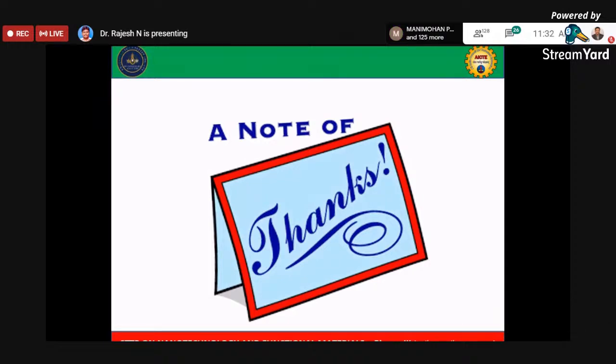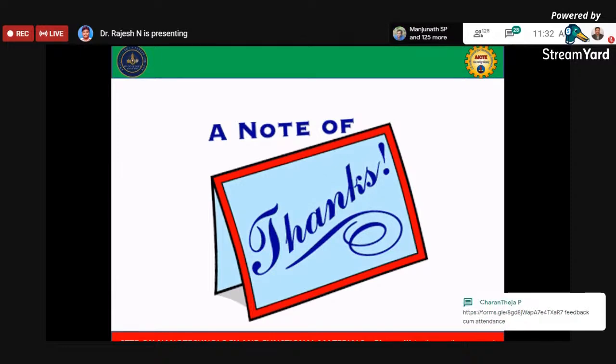And you have explained the past and present applications in the automobile field and the use of magnesium processing techniques, for example disintegrated melt deposition, the powder metallurgy route, and the microwave sintering setup, reinforcement in nano length, and more. And high performance alloys, nanocomposites, dynamic behavior, high temperature behavior, grip performance, wear rate, machinability of nanocomposites of magnesium, and saltwater corrosion.